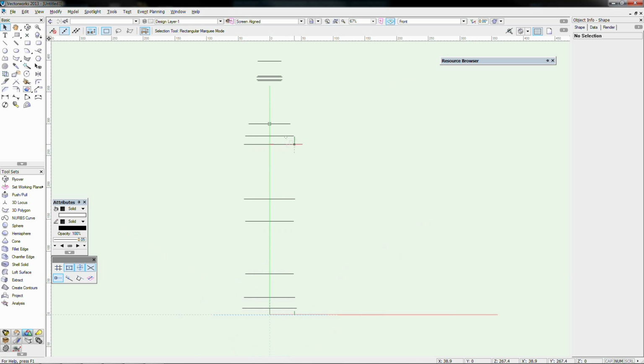But that's not really good enough. We're going to look back here in this front view, and we're going to grab the loft surface option. There's 3 different modes up here. We're going to use the first mode for this, which is no rail mode, and I'll explain what rails are after I do this. But just no rail mode in this case means that I've traced all the different cross sections of this object that I'm going to make.